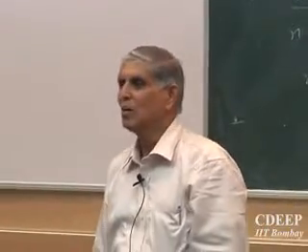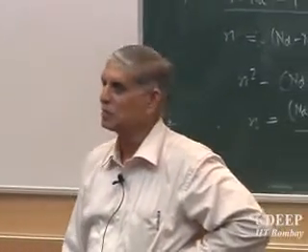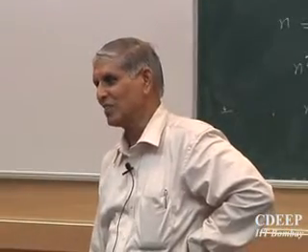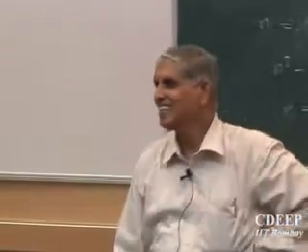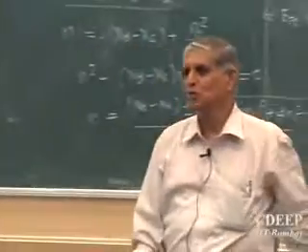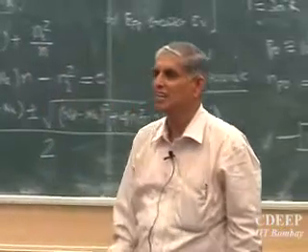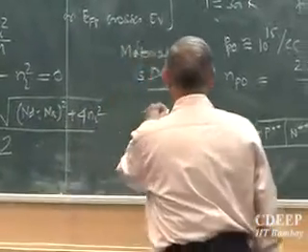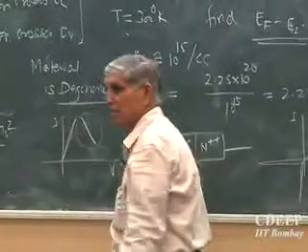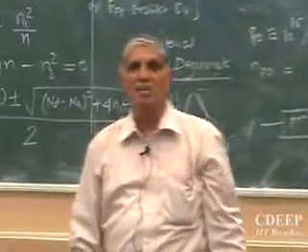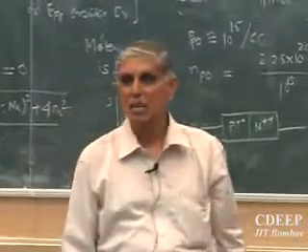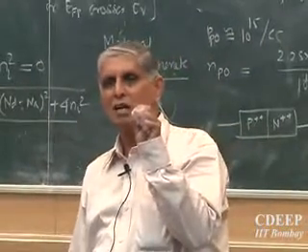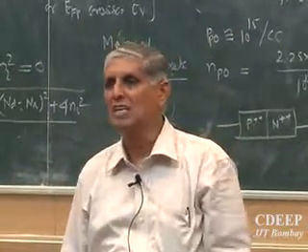Is that correct? Positive resistance dissipates power, so negative resistance must generate it. These devices therefore can be used as oscillators generating sinusoids or other waves. Whenever I can operate my tunnel diode in some form, I can actually create tunnel diode oscillators at high frequencies. The phenomenon which allows this to happen is called tunneling.